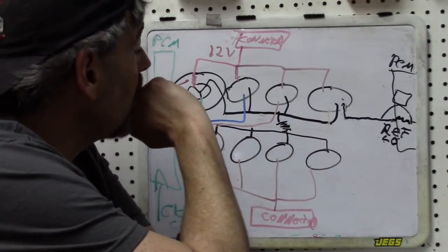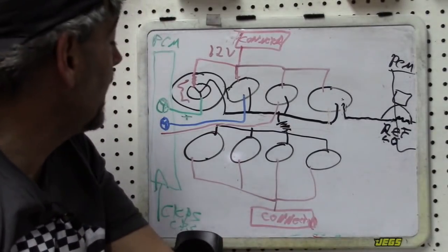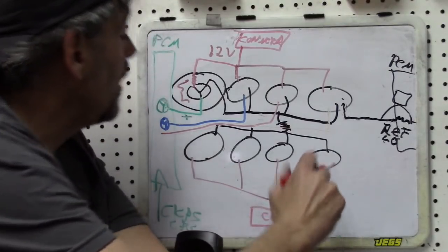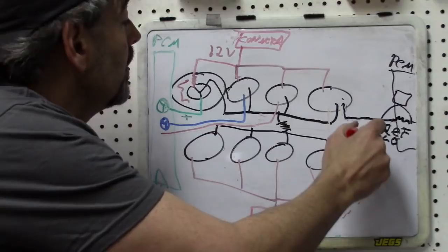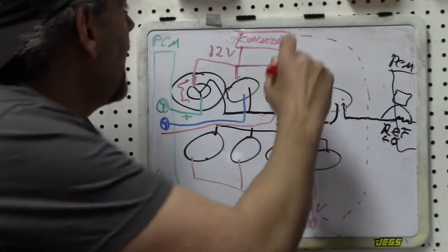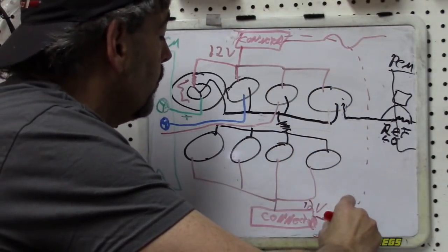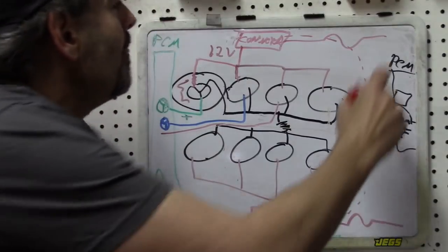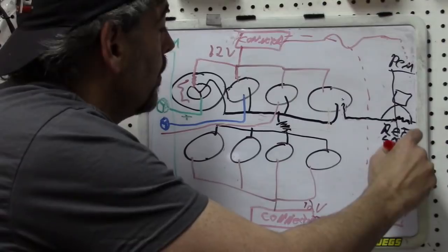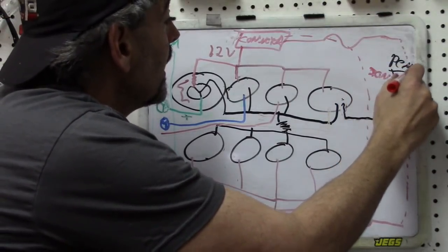One of the things also that you'll commonly see, and again, I just know this from experience, is this 12-volt positive. You would think it is the same, but I can tell you from experience what actually happens is each of these runs on their own independent fuse on each bank. And then here it's connected actually usually through the PCM with that ignition switch. So ultimately,